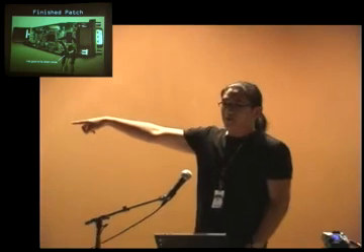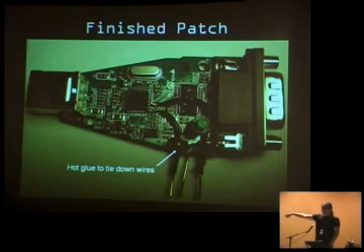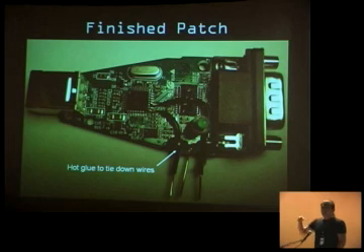You typically want to use a little hot glue or a little super glue, something to pack these wires down, because as you jiggle them around, eventually they'll come off. So you kind of just tack these wires down.